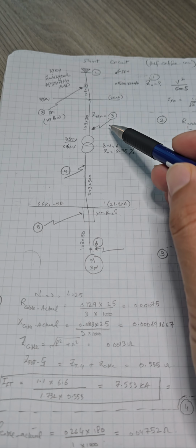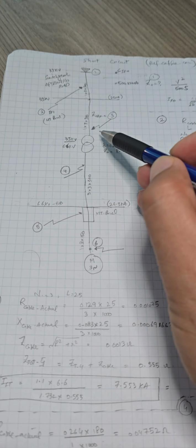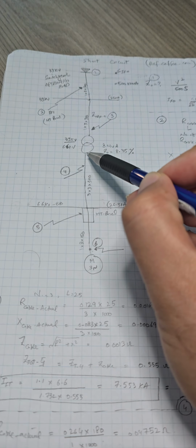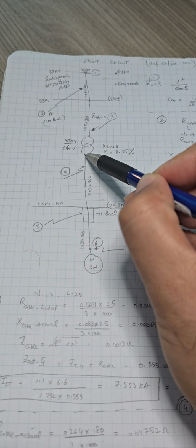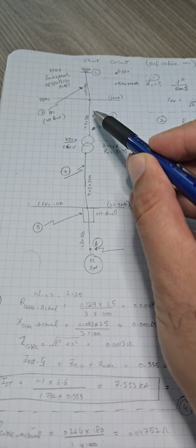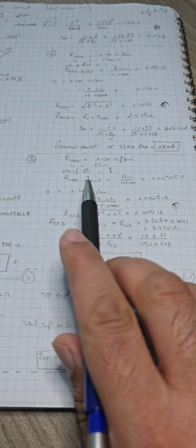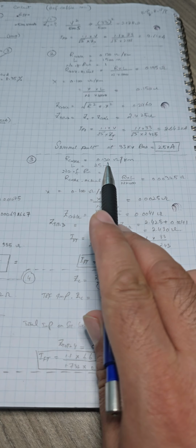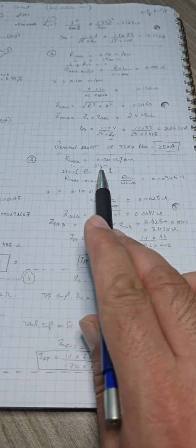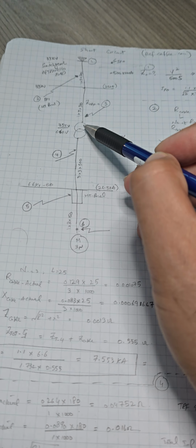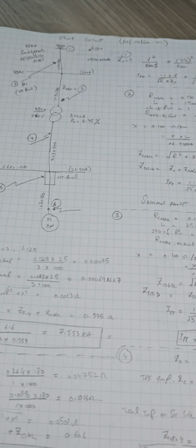So our third part is to find the short circuit rating at this point, because we have a cable, and then we will calculate after the conversion. So at this point, exactly the same formula, same concept, nothing is changed. Like we have to use the resistance of the cable, and the length is 25 meters from the bus bar till the start of the transformer.